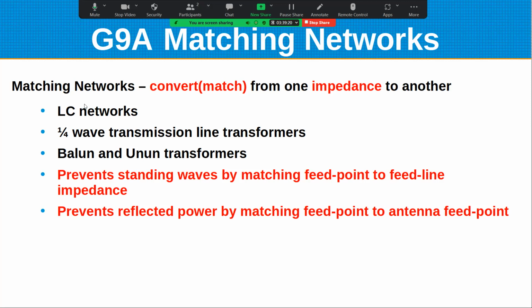And like Byron said, for end-fed wire antennas, typically you use a 49-to-1 transformer, sometimes 64, and even the next one up. The 49-to-1 to 64-to-1 are for the end-fed half waves; 9-to-1 for a random wire. Okay.